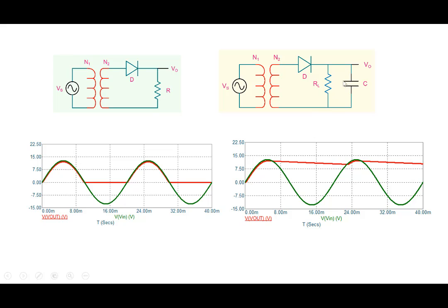So the capacitor, in the positive cycle, the diode turns on, and V0 follows the input, and reaches close to the peak value with the difference of the diode voltage. And once the input starts falling, the capacitor maintains its voltage, and therefore the diode will become reverse biased.